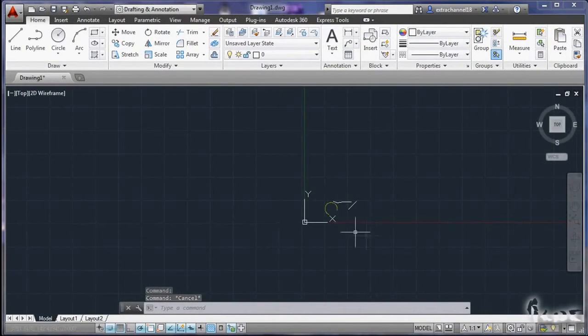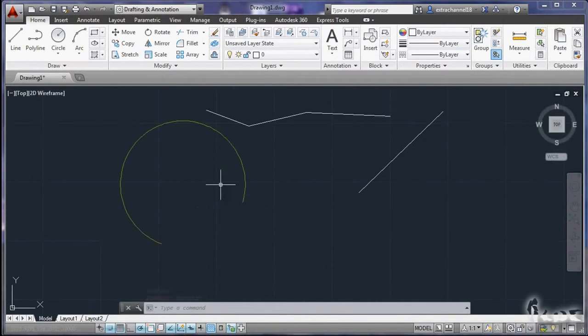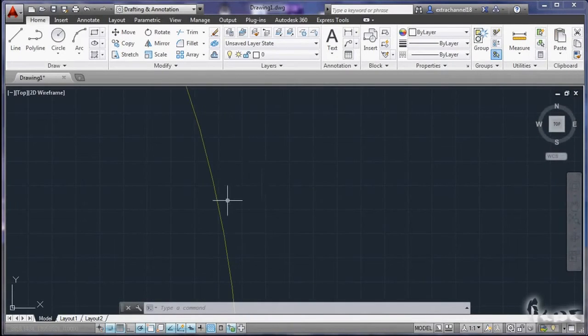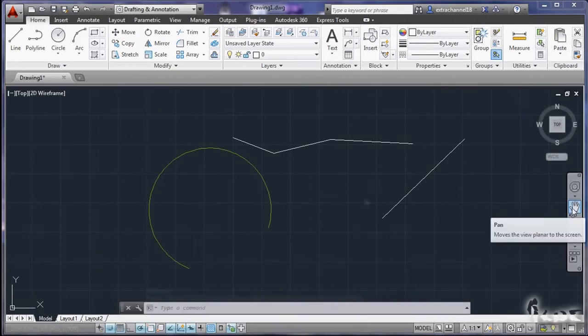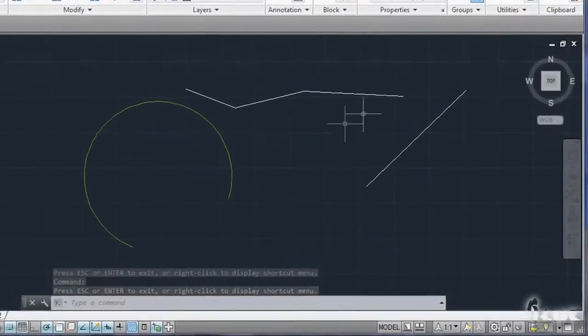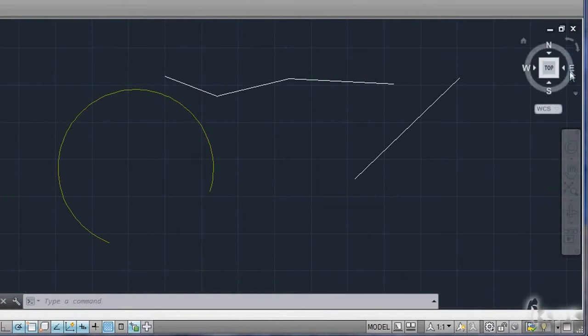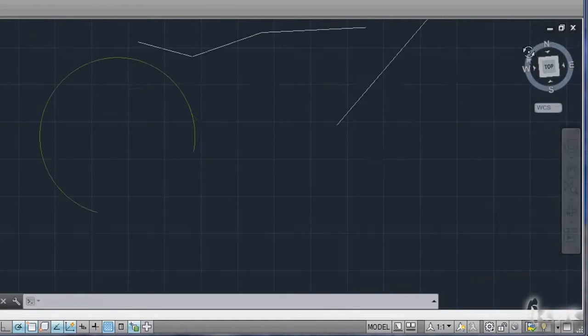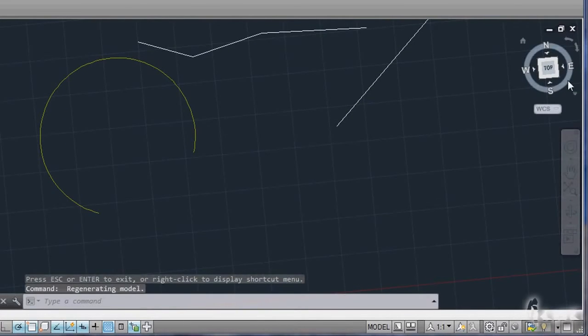is the visualization. Zoom is set simply through your mouse wheel. Use the pan button on the right to move through your workspace to check it better. To check your project, you can use the 3D map on the right. Until you go with 3D projects, the cube will show only the top face, meaning that you are watching the project from up to down. Click and drag the circle with cardinal directions to rotate your whole workspace.